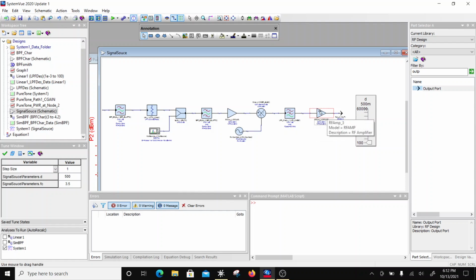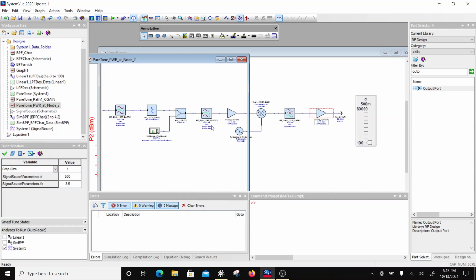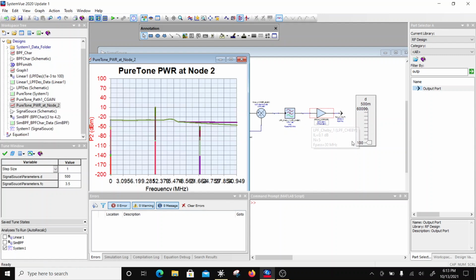So there is always a power control loop, which is basically controlling the power which is hitting the receiver. It will either vary the gain of the LNA, or it will vary the gain of the IF stage, and then you can go even closer than 10 meters, right? So that's how the higher end is achieved, by putting in a variable gain.